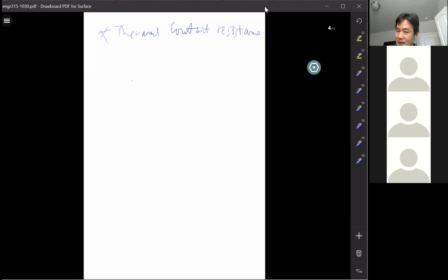Okay? It's not lost due to, don't say that. It's not lost due to, for example, the contact. No, there's a temperature drop due to the contact, but the heat is still there. The heat transfer rate, heat flow, is still there. Okay? So that's the physical behavior, the temperature distribution inside these two materials A and B with the contact.